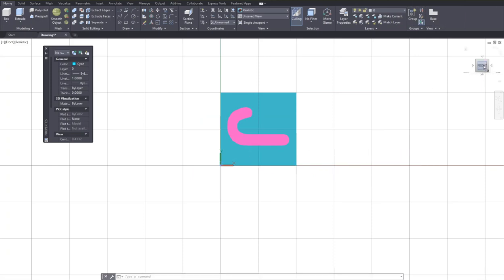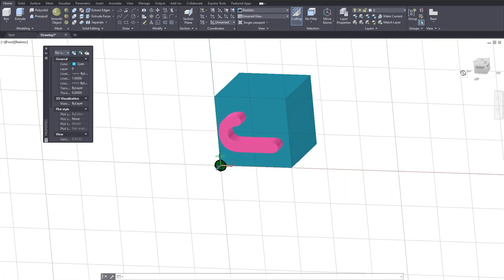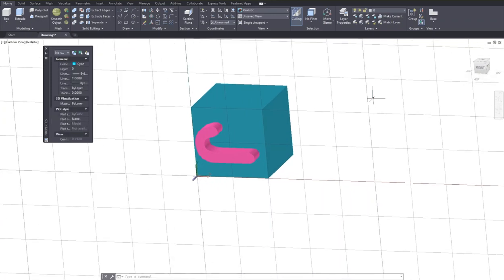That concludes the significant part of the precision tools. At the lower right-hand corner, please pay attention. You have a number of options here, and you don't need all of them all the time, but the object snaps are absolutely important. You have ortho mode, and you have three-dimensional ortho mode, which is very important. There's also UCS detection mode. When you're dealing with surfaces, you should definitely turn it on.